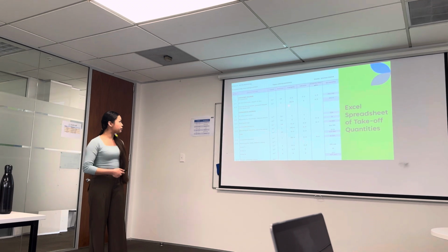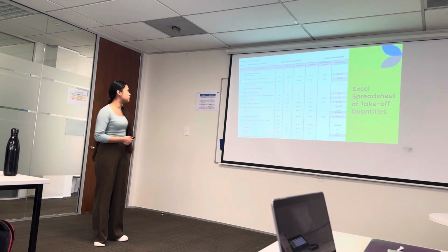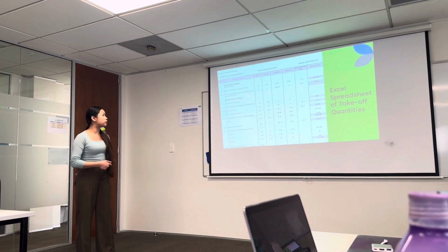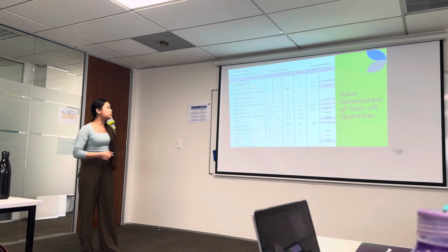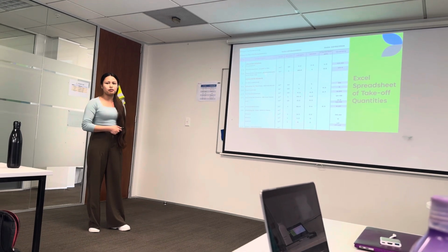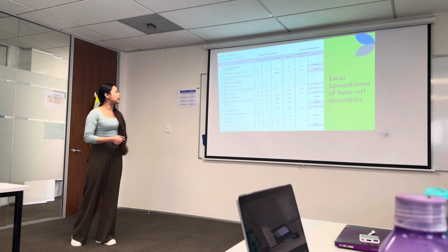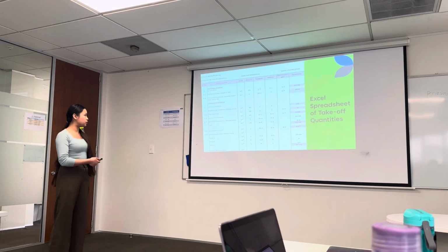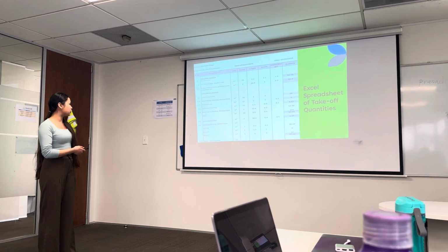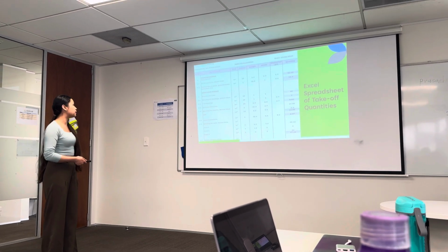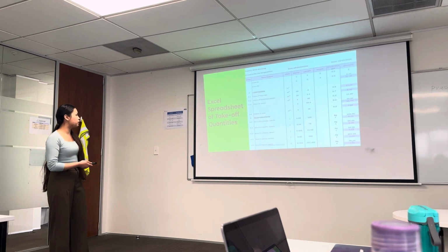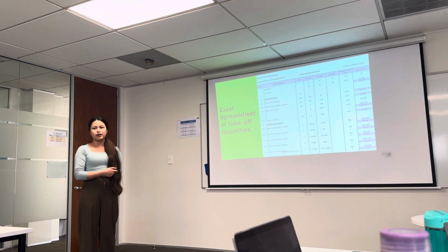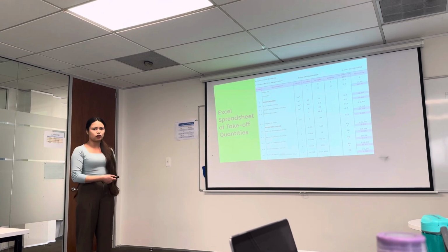So for example, in the groundworks for pit excavation, the depth is 1 to 2 meters. So we consider the 1 to 2 meters we mention here as per the standard method of measurement, and the factors, and we calculate it into the quantity, and the quantity is in meter cube, as you know the unit. So as for the concrete works, attached beams, all are the same. And this is also for the quantity takeoff. The remaining is reinforcement that I have mentioned, that the reinforcement we take as the ton.